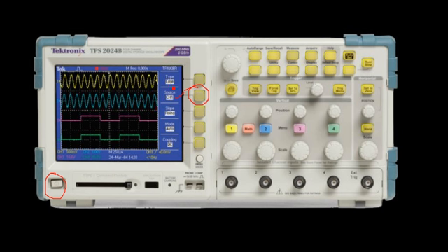So based on the channel that you select, you can now set different modes of operation, and you can go for coupling, AC coupling or DC coupling. Then you can set the trigger type, etc. So there are different options that you can set for a single channel. So the channels are provided here, 1, 2, 3, 4 channels are here, and you have an external trigger option also. So these 4 are the buttons or knobs for adjusting the voltage levels or y-axis control, and time period is controlled using this dial.